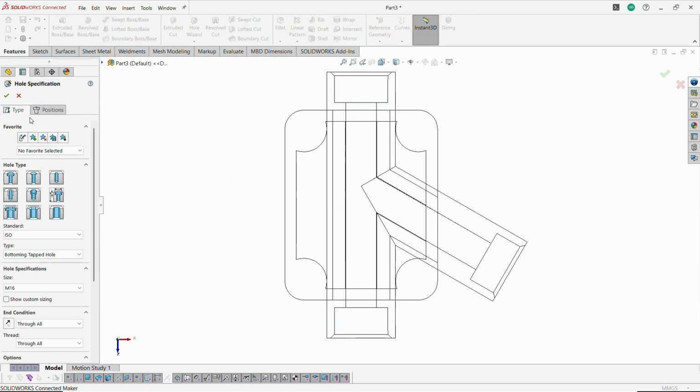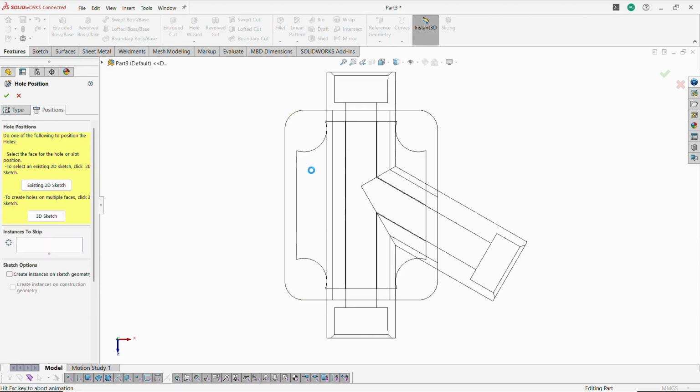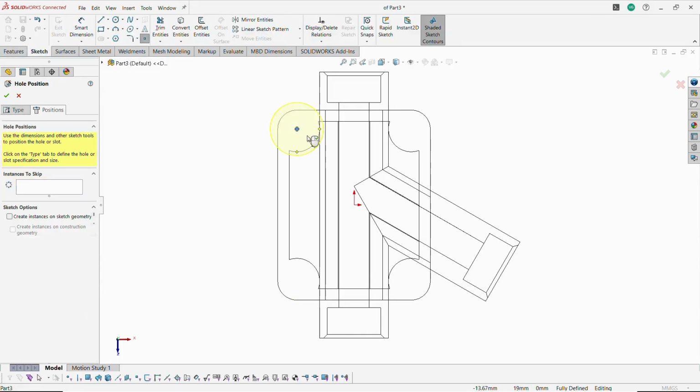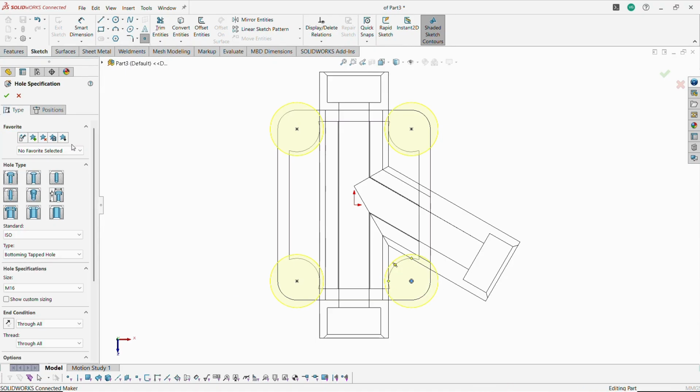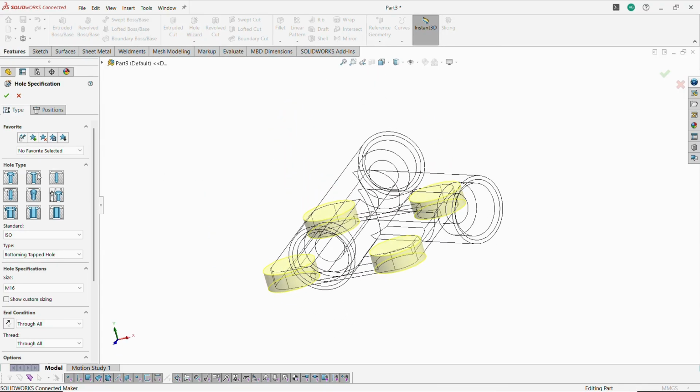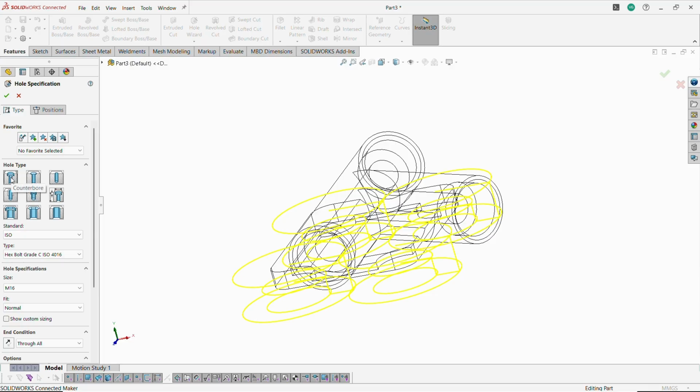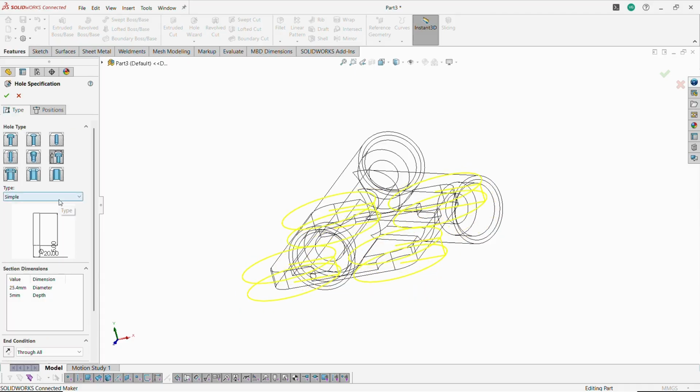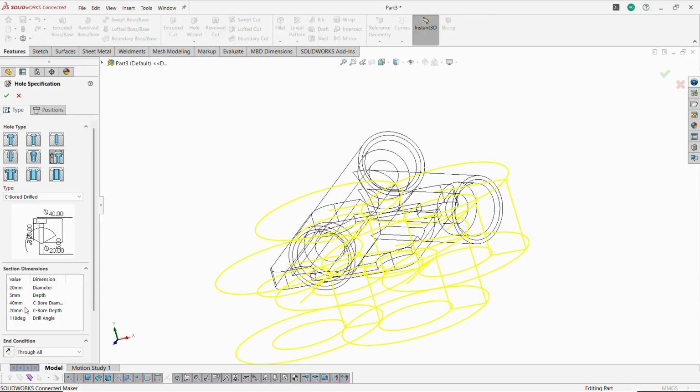First we need to position the sketch. So choose the positions, selecting the top faces and selecting each of its concentric points from the primary circle. So selecting the corner points from the primary circle. Then we are going to choose this particular type called legacy hole. Instead of choosing a default counterbore and hole type, I prefer this legacy hole counterbore drill type. Let's change the dimensions now.